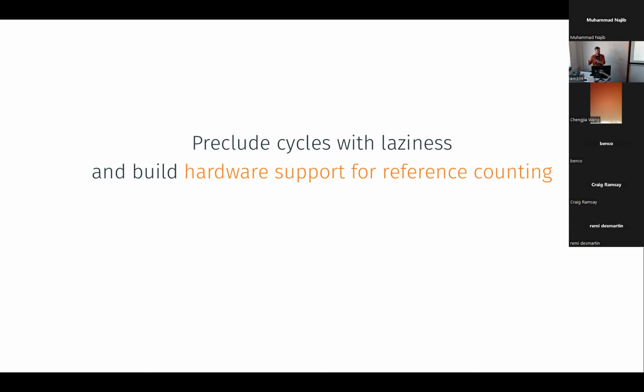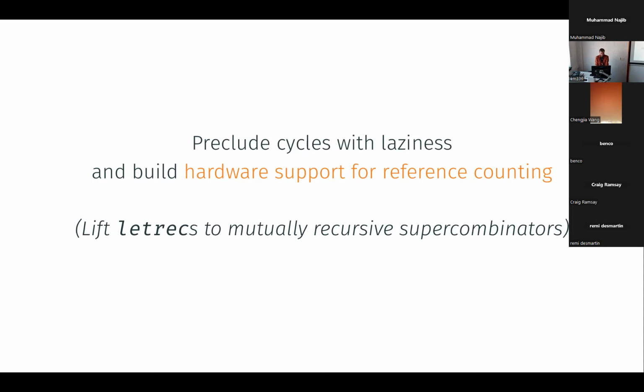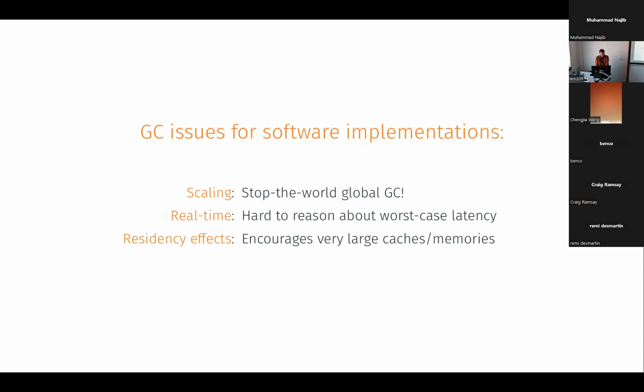We've got this carefully tuned core for the reduction, where any damage to the clock frequency on that would really hurt us. But with the reference counting, we can do it off to the side in a pipelined, entirely separate bit of circuitry. The other reason that is kind of neat, I think,